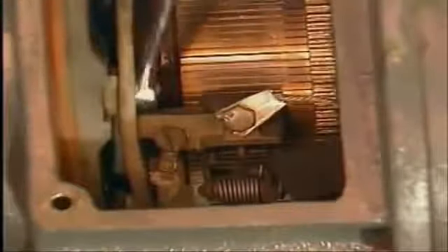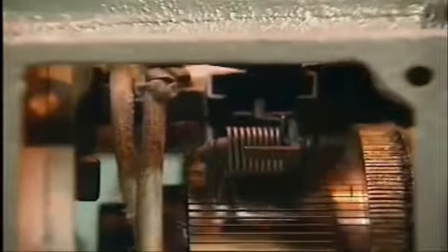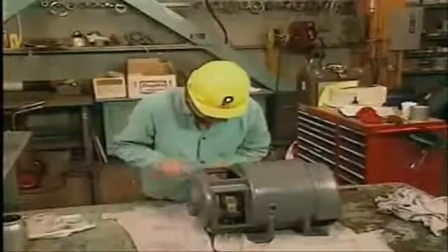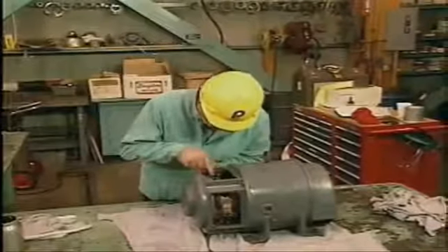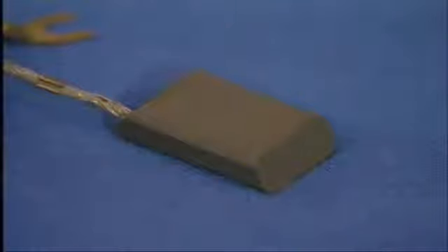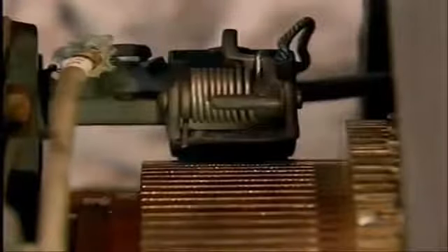The brush rigging is adjusted by loosening the brush holder bolts and then moving the holders so that the brushes cover as much area as possible. After the rigging has been adjusted properly, the brushes can be replaced if required. If new brushes are being installed, they must be the right type and grade for the motor as specified in the motor manufacturer's manual. The brushes must be properly seated in their rigging. In other words, the shape of the brush's bottom should fit the shape of the commutator.